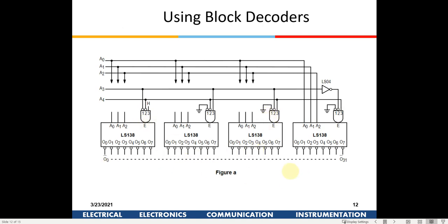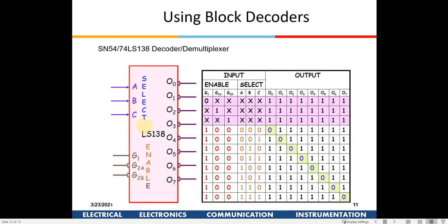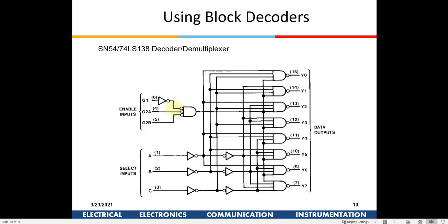Is this understood? Here for each 74138 chip, we are giving an AND gate as an input to the enable. Is there an AND gate out there? Yes, this AND gate is internal. We are not giving it externally, but it is an AND gate implementation.